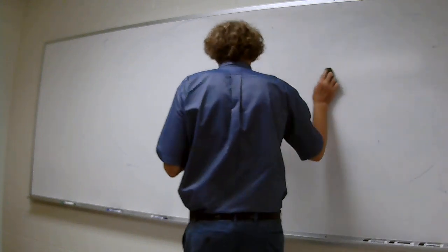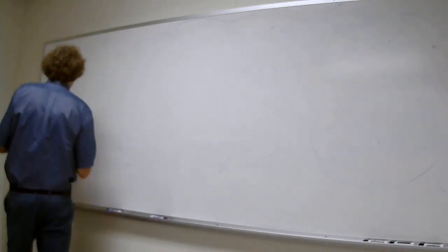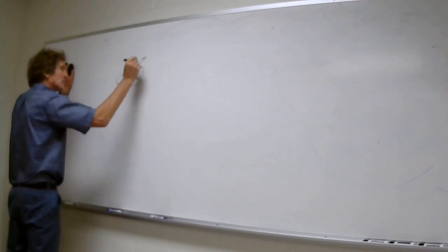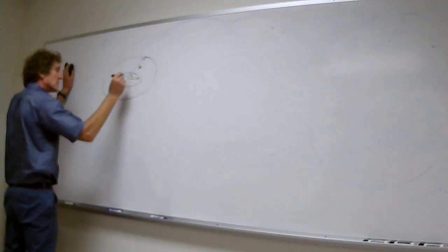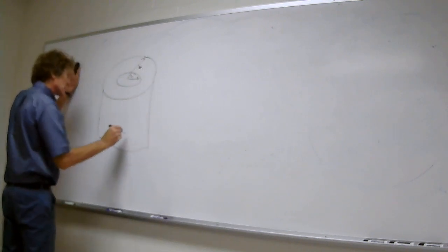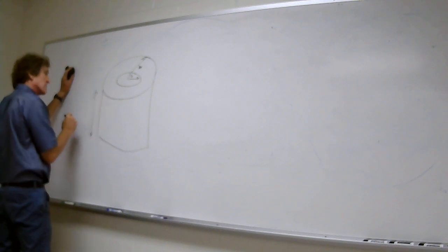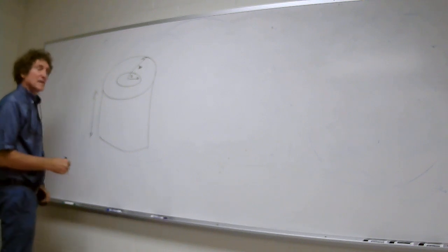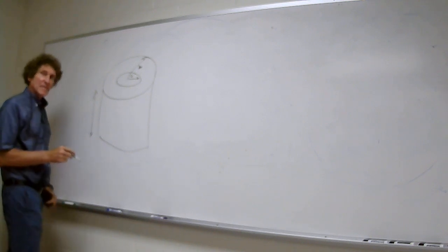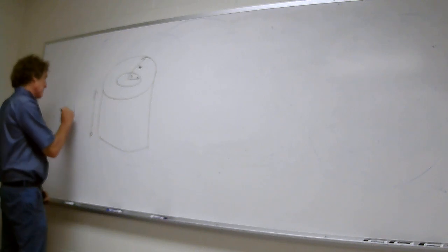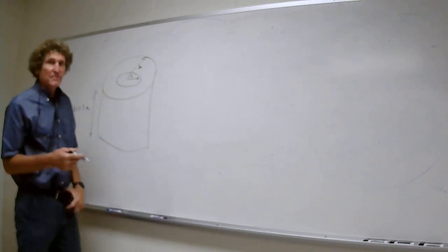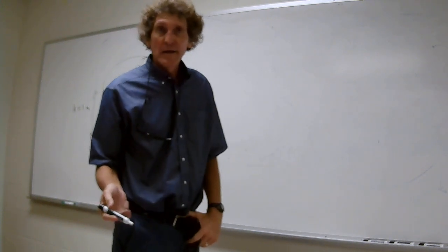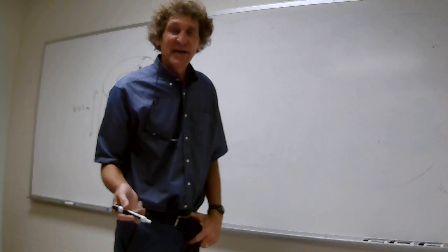Suppose a coaxial capacitor with inner radius 1 centimeter, outer radius 2 centimeters, and length of 1 meter is constructed with 2 different dielectrics. Oh, this is going to be parallel capacitors, I think. Height H, 1 meter, that's how tall it is. Half of it is made of epsilon 1, half of it epsilon 2? Yeah, half of it epsilon r is 9, and half of it is equal to 4.